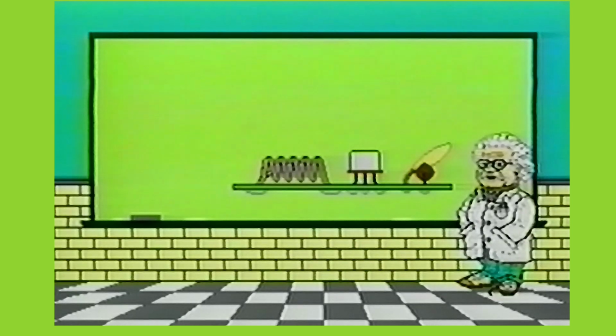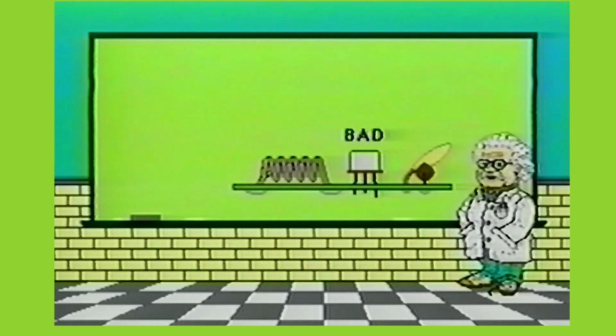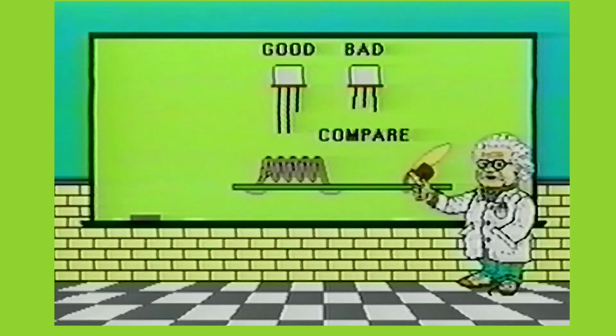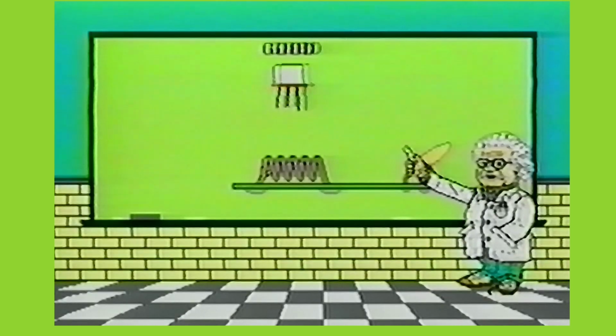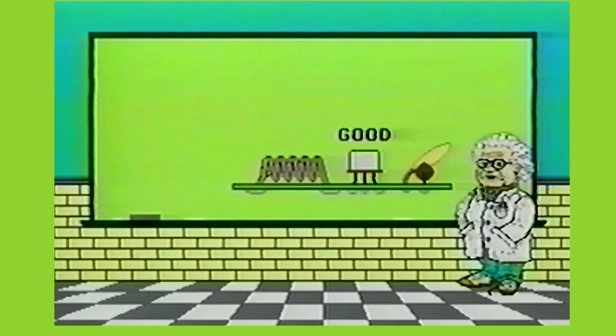When a component is replaced, its leads must be the exact length of the leads replaced, and the leads must be placed back in the original component's position. Even when troubleshooting the RF stage, care must be taken not to move the components on the board, or the circuit may go into oscillation.